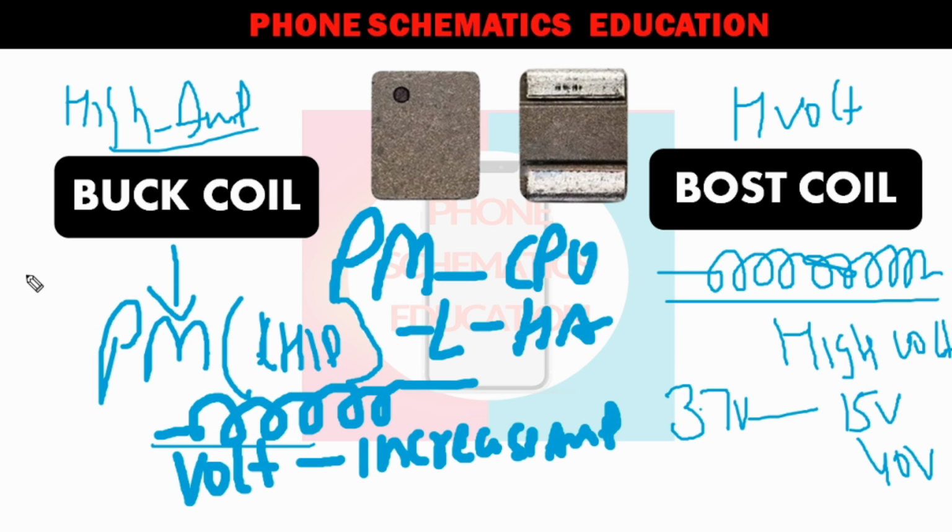If you use a normal multimeter with continuity mode, beep mode, or diode mode together, the multimeter beeps on a coil, and some technicians think it is a short and inject voltage on it. After that, the CPU, your master IC, will be gone forever.